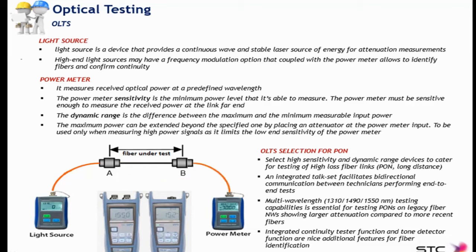Once the zero level is set on the power meter, reconnect the connector at the original position, and the figure that is shown on this power meter screen is directly the attenuation between A and B, including the connector B attenuation. In this case, the attenuation introduced by connector A is not taken into account. So it will have to be added. This is the way this device operates to measure relative power.